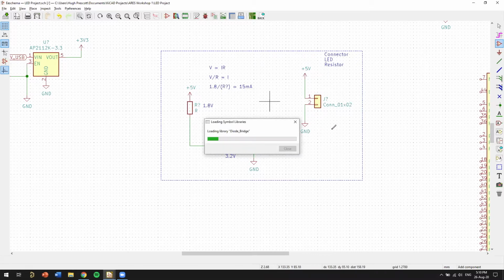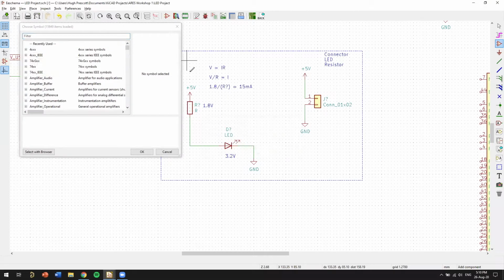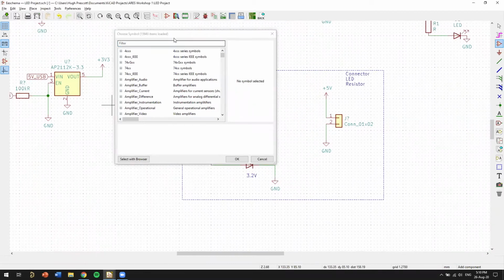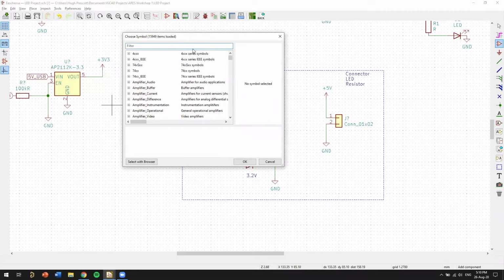If you click this part here and then click anywhere in your schematic, it'll bring up the symbol library. I think last week we had an issue where for some people the libraries weren't loading. The first time you download KiCad, it will probably ask you to import the default libraries. You want to say yes to that, because KiCad is open source, and people are constantly adding new parts which are found on DigiKey or whatever supplier you typically would get parts from. They'll always be adding accurate components to this open source library.